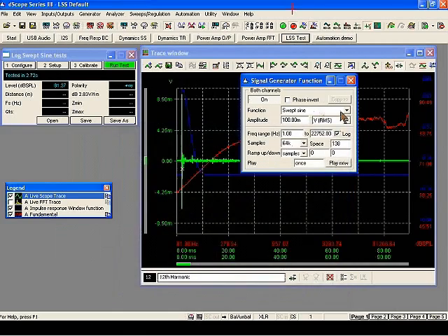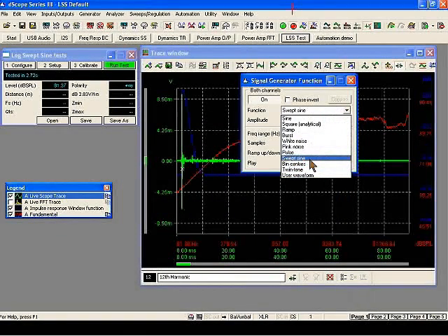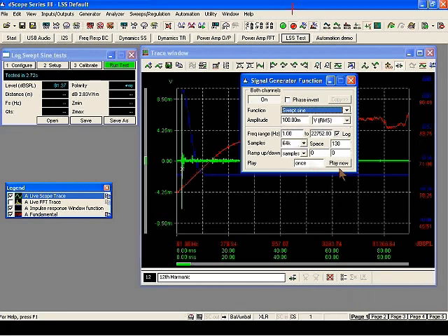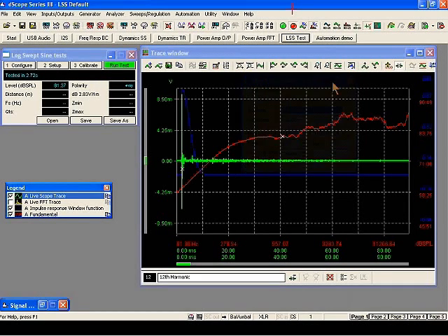So this is our chirp stimulus, our fast swept sine, and in this particular case, I have set up a logarithmic sweep rate. Now, some of you may know this already, but the primary reason for using this particular stimulus is that when we use a logarithmically swept frequency in the swept sine stimulus here, that allows us to do more than just simply analyse the fundamental frequency response of our loudspeaker.